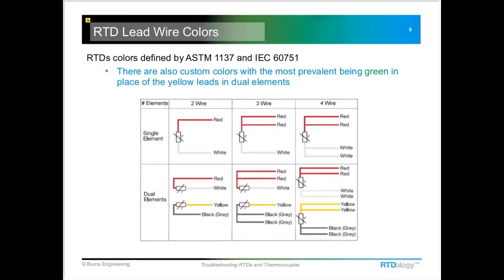And then we had a little more detail here about how we know what is a correct wiring connection to your chart recorder or a controller. There are some standards for RTD lead wire colors. Not all the manufacturers follow these exactly. They'll have some of their own codes.